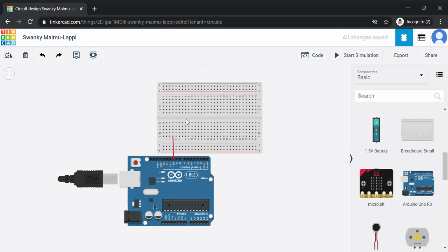To check connectivity, you can look for these green highlights that appear. Anything that's green is connected to the pin you're hovering over. So I can see this entire column here is connected, and this entire row here is connected. From this wire, if I follow it, it comes from pin 10, and this entire row is now connected to that pin through this wire. These two rows are not connected, so if I wanted to connect them together, I'd put another wire. Now you can see that there's a path for current to flow.